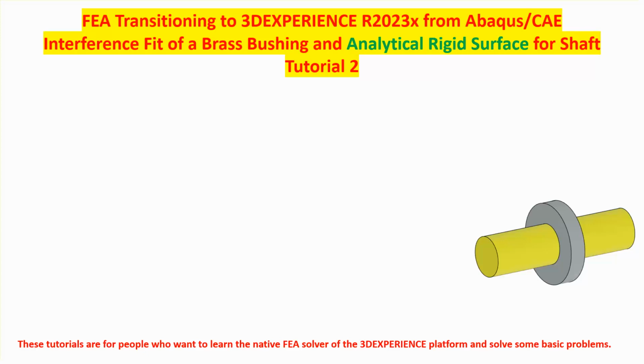So you may be tempted to say, okay, analytical rigid surface then is better to use than the rigid shell elements. Then why the first tutorial? The problem is that analytical rigid surfaces must be either surfaces that are obtained by extruding a curved two-dimensional curve, or revolving a two-dimensional curve about an axis.